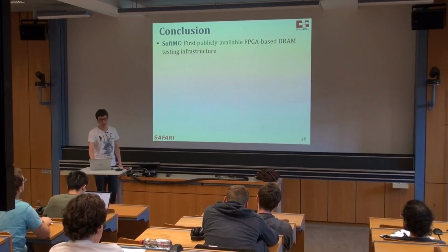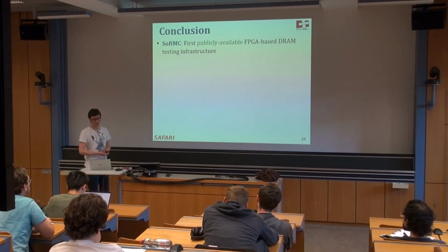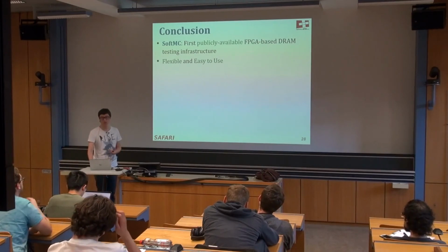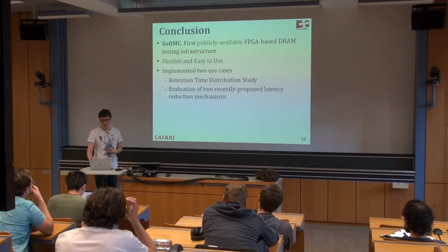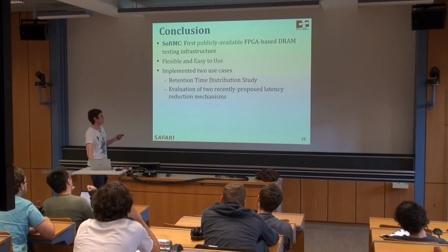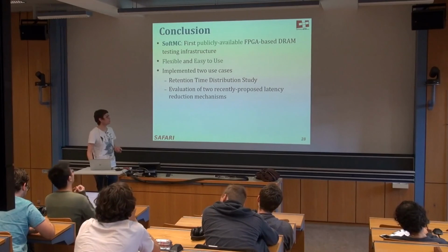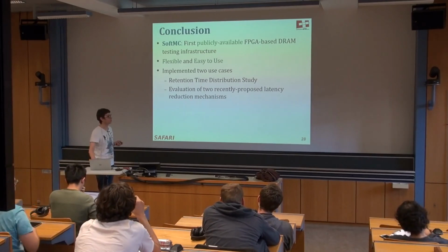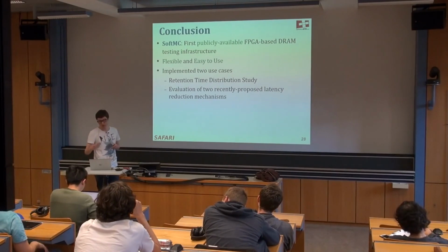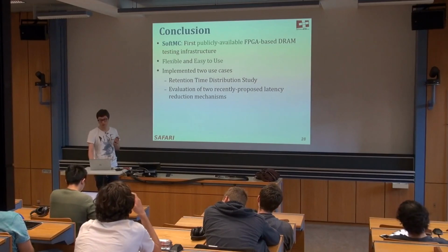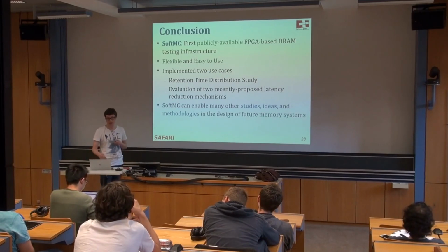Okay, and as a conclusion, SoftMC is the first publicly available FPGA-based DRAM testing infrastructure. It is flexible and easy to use. You can issue any DRAM commands to the DRAM with precise timing. And we showed 2 different use cases for it, right? The first one was to show the correctness of it, and the second was looking at whether the assumptions of 2 previously proposed ideas were correct.